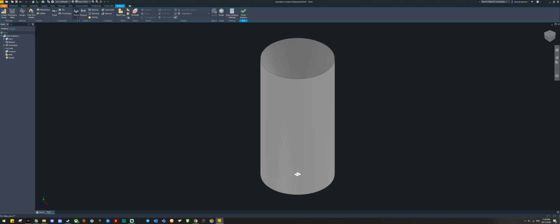And then select load, go for force. You can go force or pressure. In this example, I select force. Select this area on the top, and we go for 1000 Newton. Select OK.